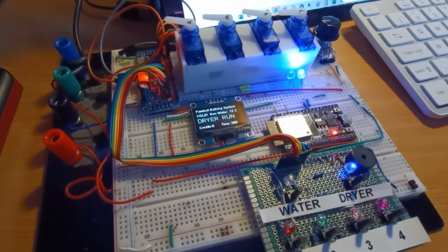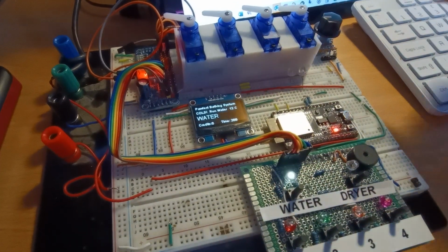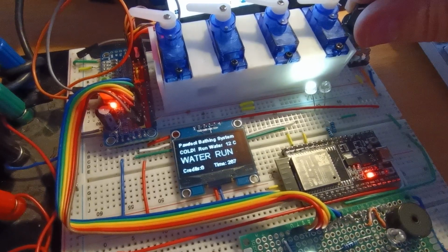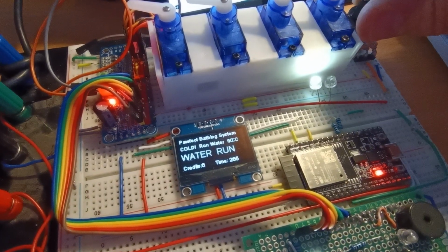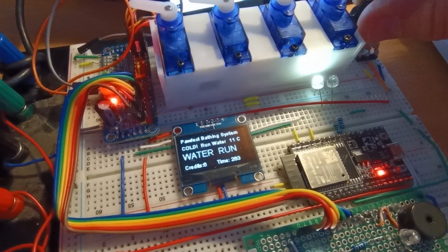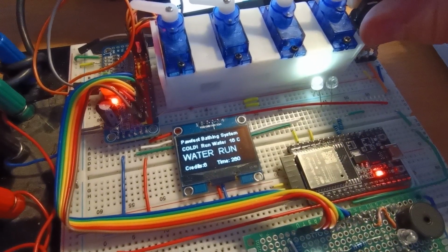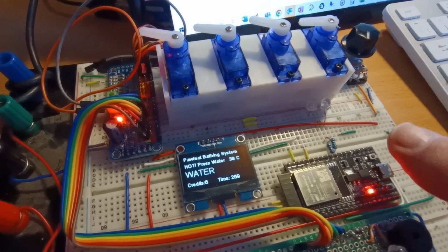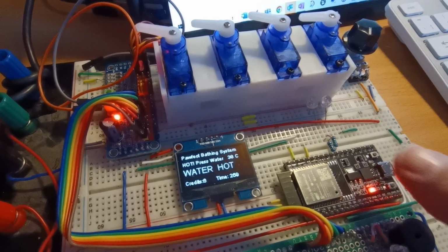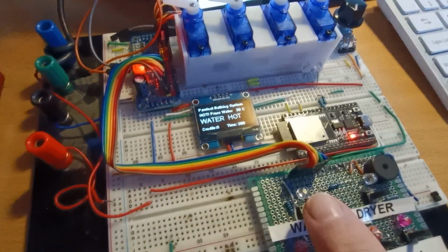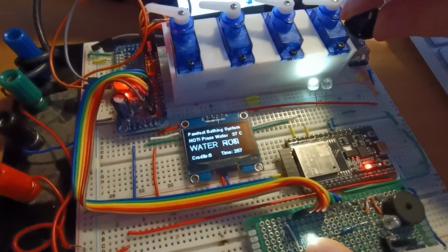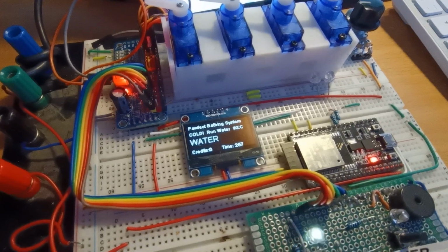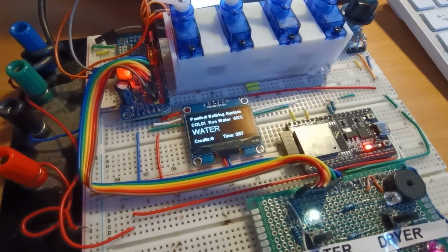If the water starts to run too hot or cold, if the water is running cold, then it's not really a problem. It will continue to run. You can see I'm just simulating the temperature change on the display there. However, if the water gets too hot, all of a sudden now, if you notice, it's shut off the water completely, and the user can press and hold the water control button until that temperature drops back down to normal again, which it has there, so it can now go back into normal mode again.